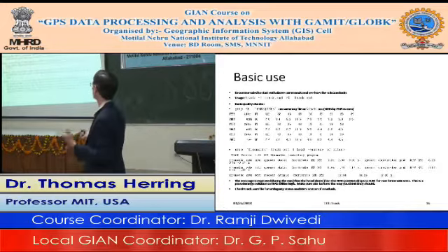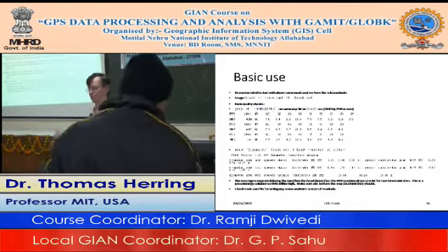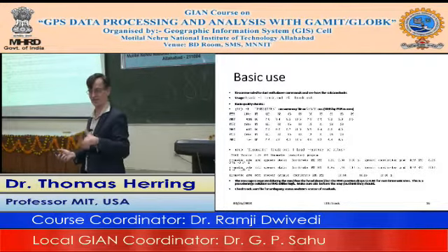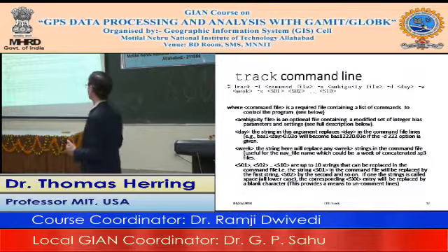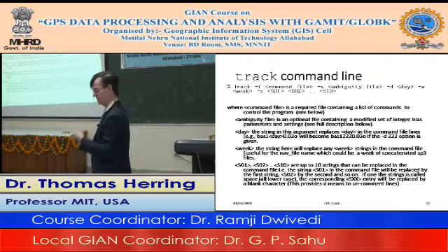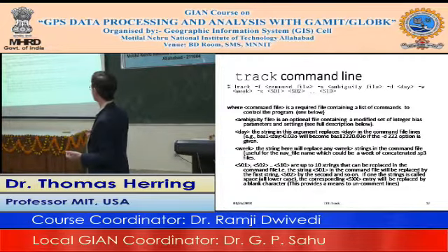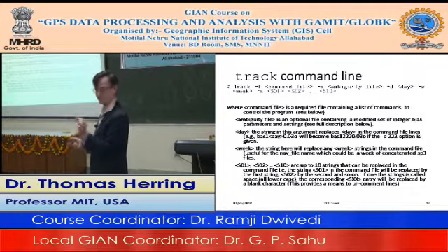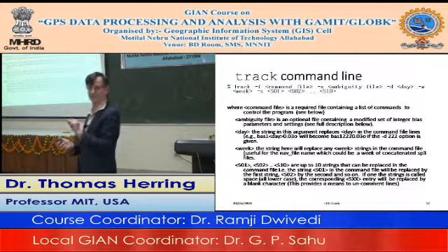Normally it is the day of year for the RINEX files. Sometimes there's also a -week entry, which would allow you to reference the SP3 files, for example, by the week you're using for the orbits. And then it has a generic set of optional strings, which you just give different values for, and again these get replaced. We use this to do file naming inside.